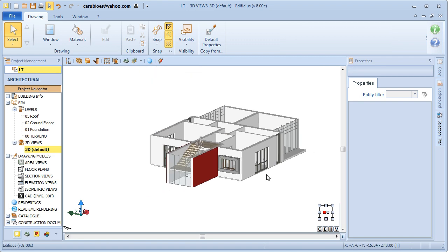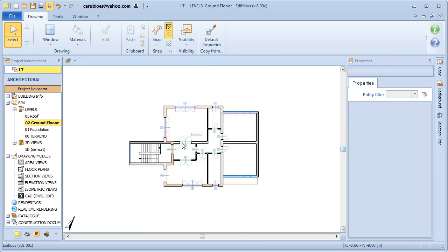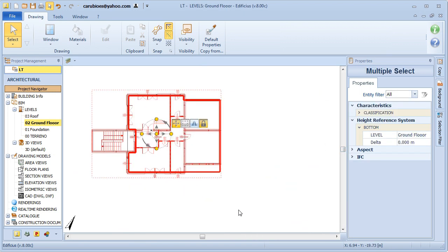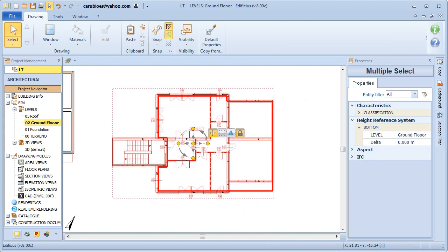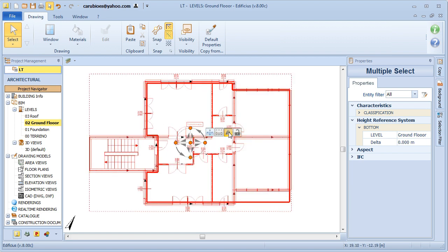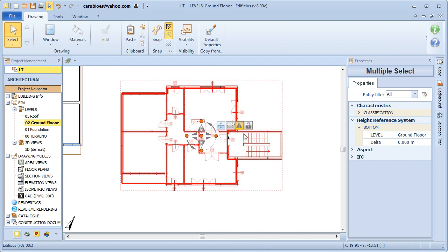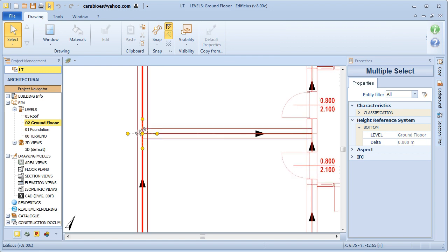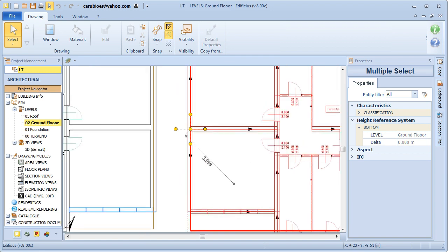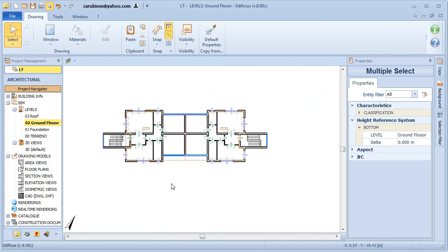How about mirroring entities? Let's see how to make a symmetrical copy of our model so as to finish off the modeling of our floor plan layout. As you can see here, this is a quite simple process. It requires a simple copy-paste action. Then all we need to do is simply use the 2D object grip here and place the copy models at a desired point. So as you can see, we have terminated our floor plan design.